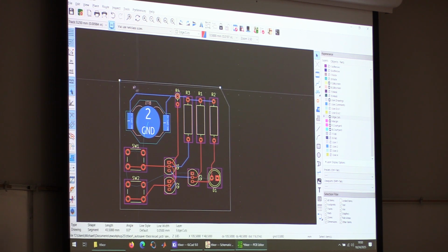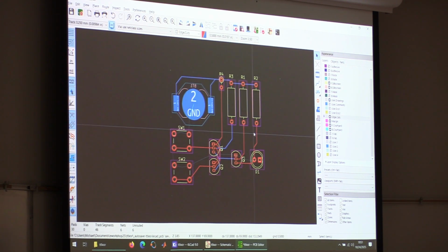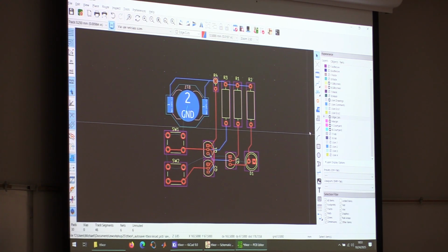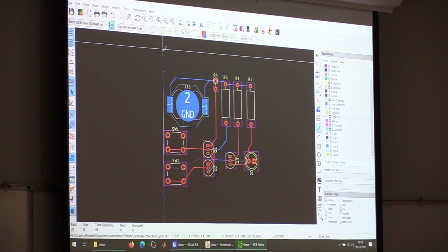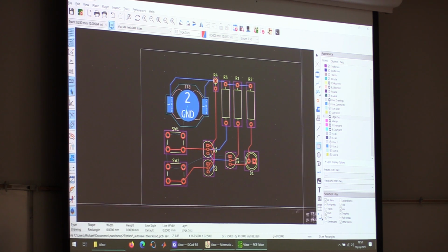Yeah. Well, here I kind of ran through that really quick because I realized I forgot to do it at the start. But here, I'll delete the edge and I'll go through designing the board shape. So to create your board, say I want specific dimensions, I can select edge cuts, and under edge cuts select draw line. Alternatively, you could also draw a rectangle. I believe that works too.